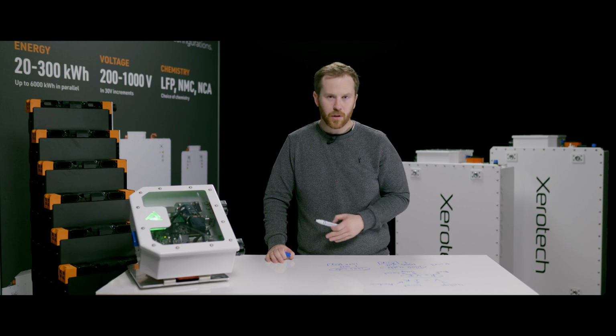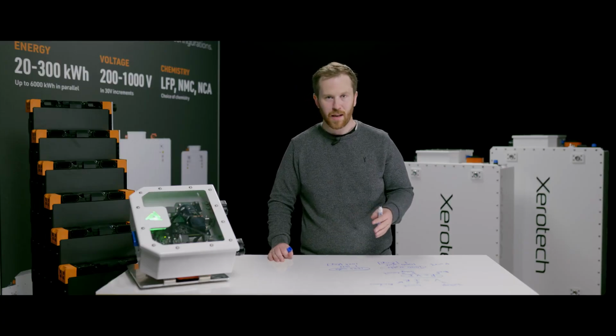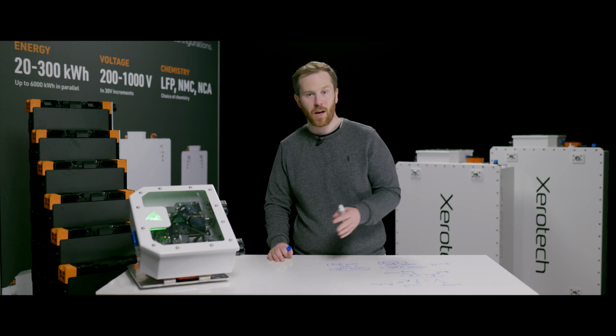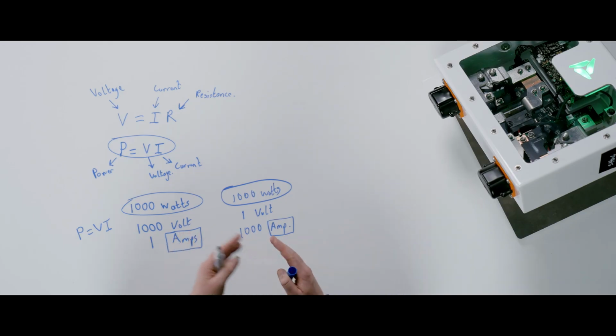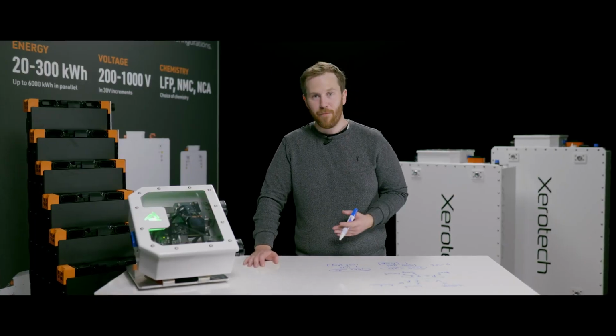When it comes to voltage, it's a lot easier to have higher voltages than it is higher currents. So for example, a few millimeters of insulation on a wire can provide thousands of volts of insulation. So there's not that big of a difference to go from 10 volts to 100 volts to 1,000 volts. It's a lot easier than going from 10 amps to 100 amps to 1,000 amps. So the big advantage of going to higher voltages is you can achieve higher powers with smaller conductors and lower amounts of amps. And you might say, why don't we make everything high voltage?